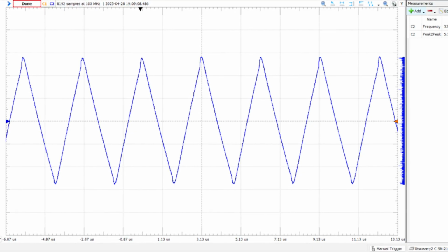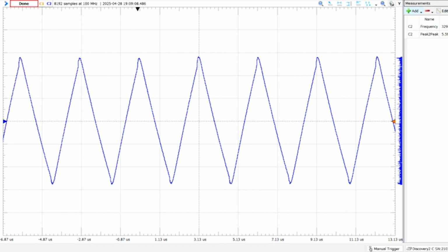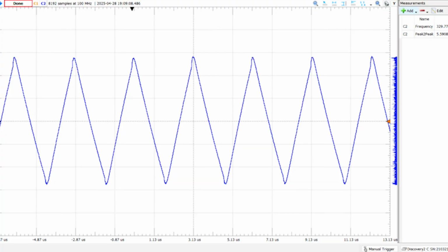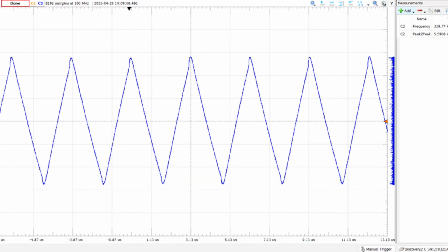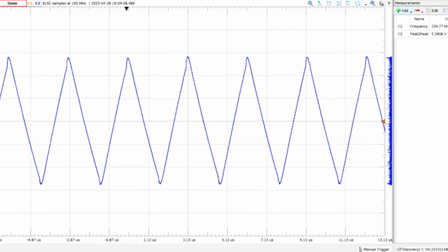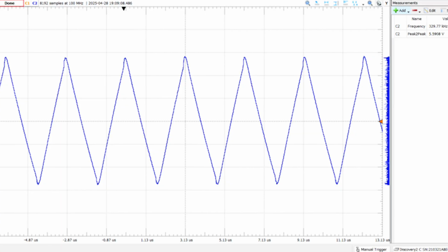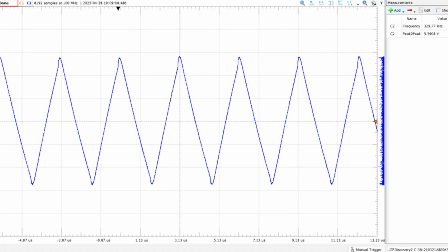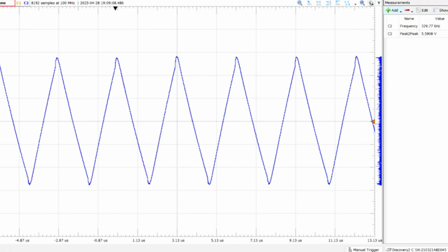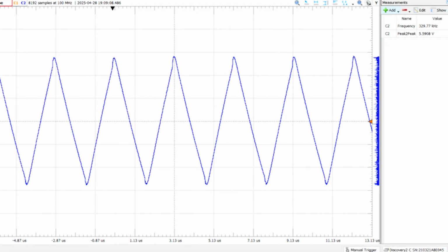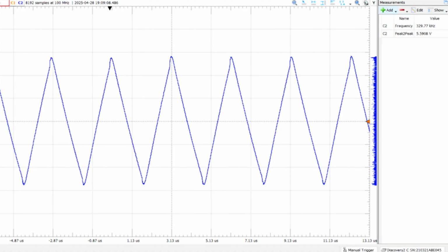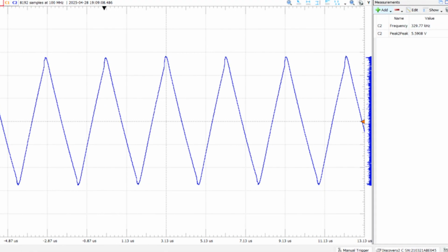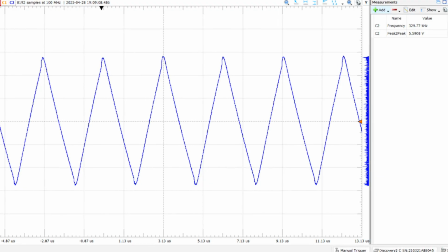All right, so now that we've taken a look at subcircuit 1's schematic, let's dive deeper into the output signal. The final triangle wave with a frequency of 330 kilohertz and a peak-to-peak voltage of about 5.6 volts can be seen here. The slight asymmetry in the wave is caused by the input square wave's imperfect duty cycle of 54.4%, resulting in uneven rising and falling slopes. But this distortion is very minor and it will not significantly affect performance since this waveform is only being used as a reference in the comparator for PWM generation.